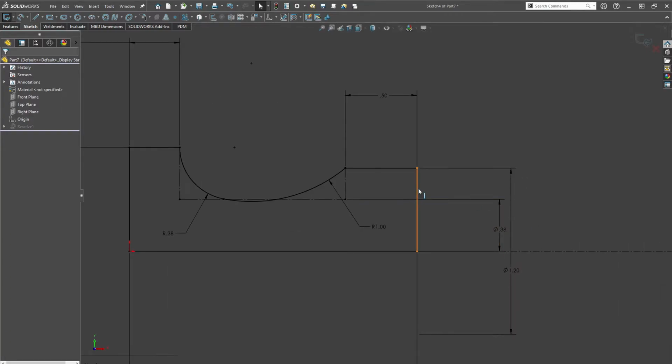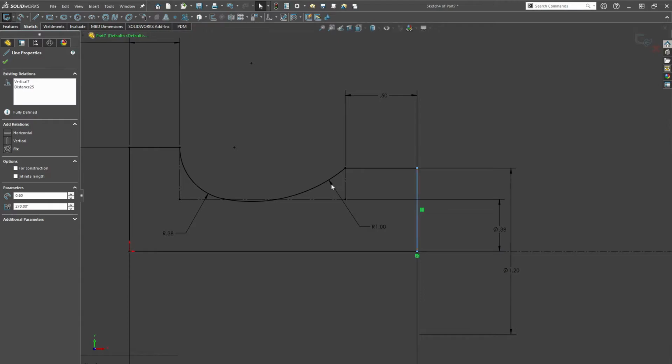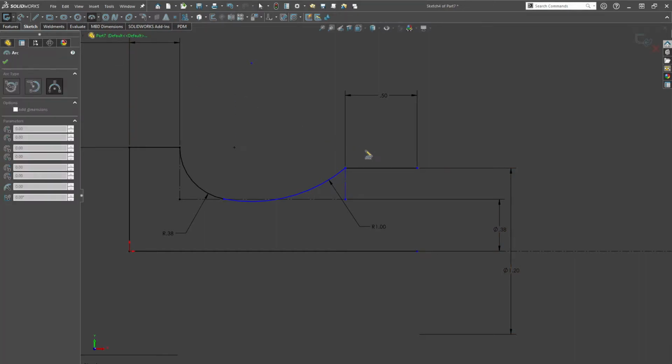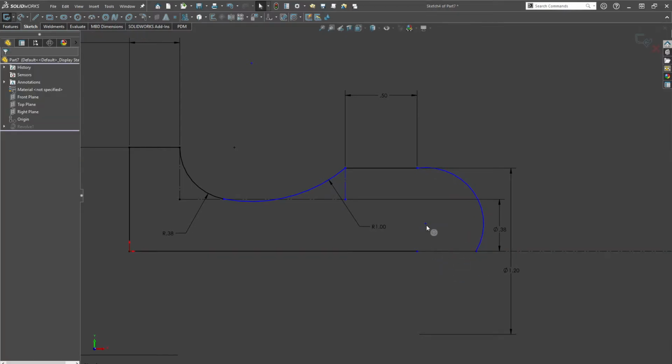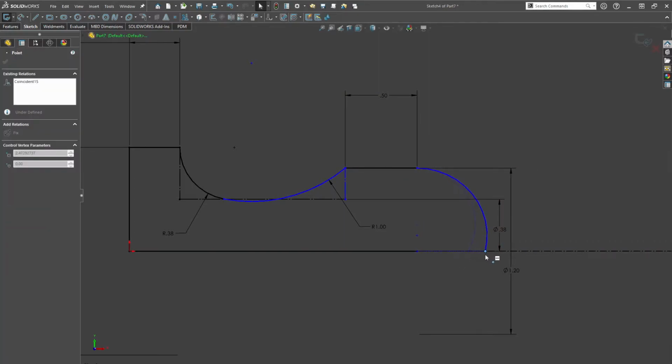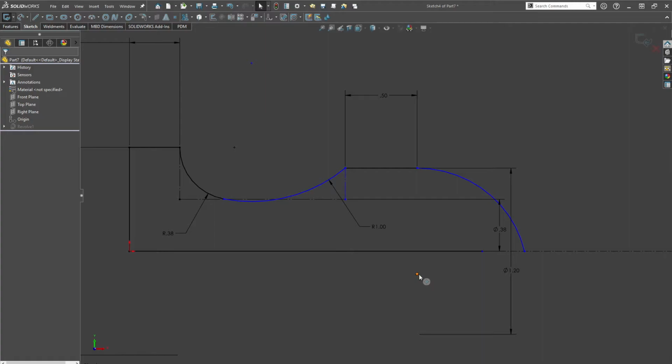For the head of the pawn, let's say we want a full sphere. Well, you can do it with the fillet tool, but it's a little bit easier, I think, if you just use the sketching for the revolve. Once again, I'm going to use an arc, and I'm just going to come up like this. I'm going to bring this point and this point, they will be tangent, and then this point will be coincident with this line, and we will join those points together.